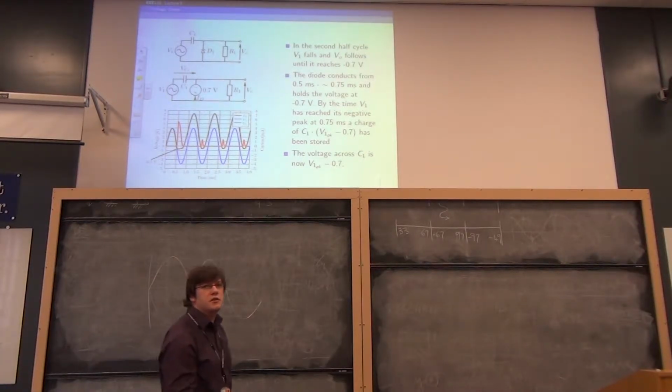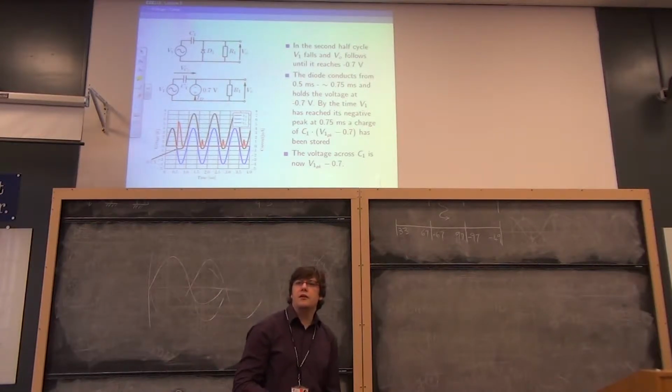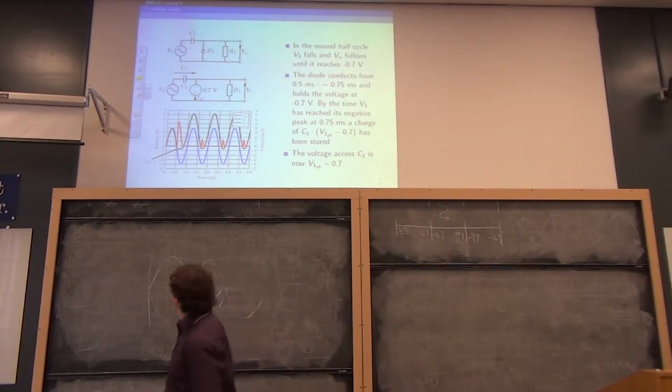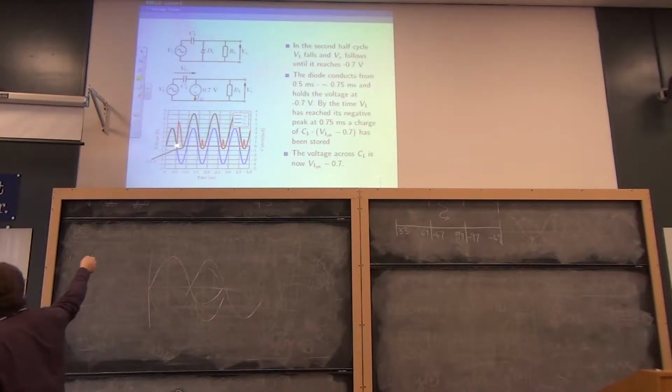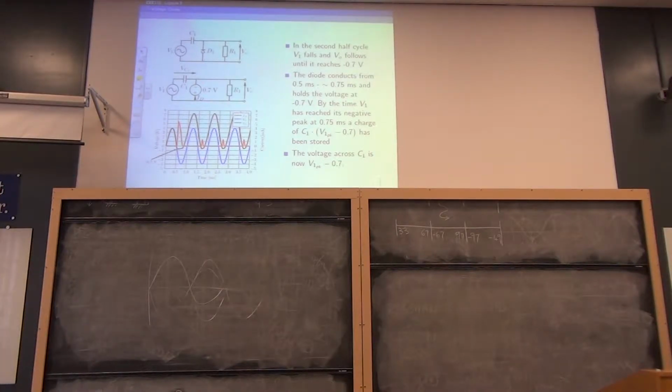The resistor will charge the capacitor very slowly. The diode can do it very, very fast. And there'll be some charge, and the charge is the integral of the red one, which is current. And having done that, by this point, there will be a voltage across C1 which is not insignificant. That's to say, it makes a big difference as to what's going on in the circuit.